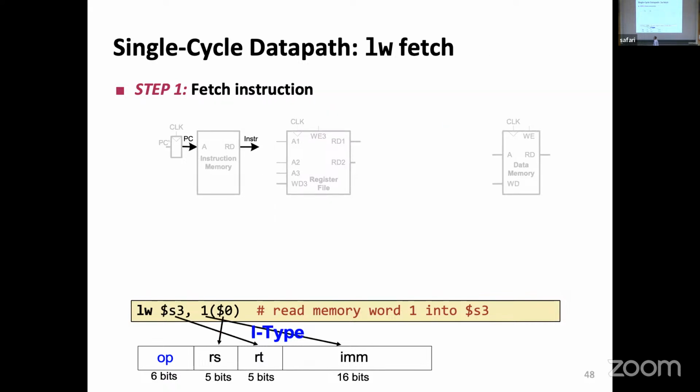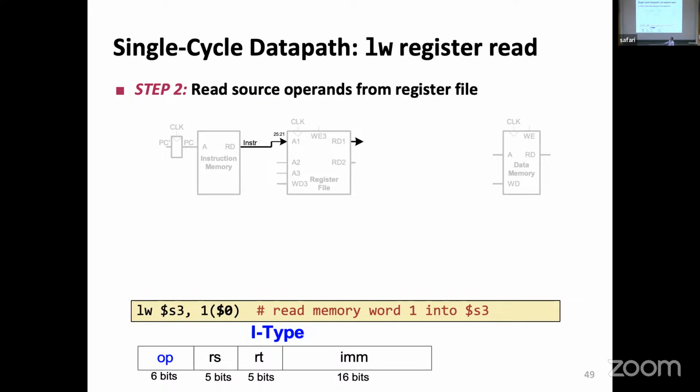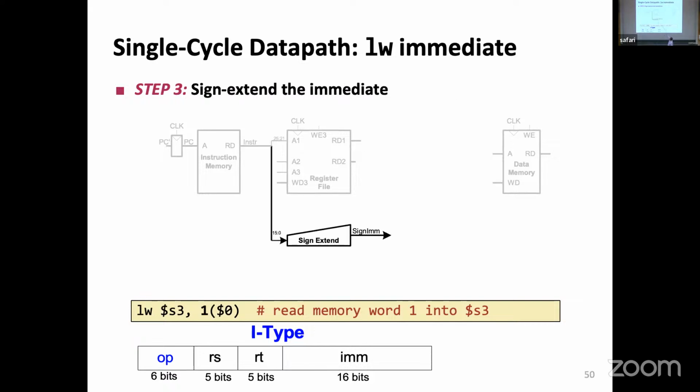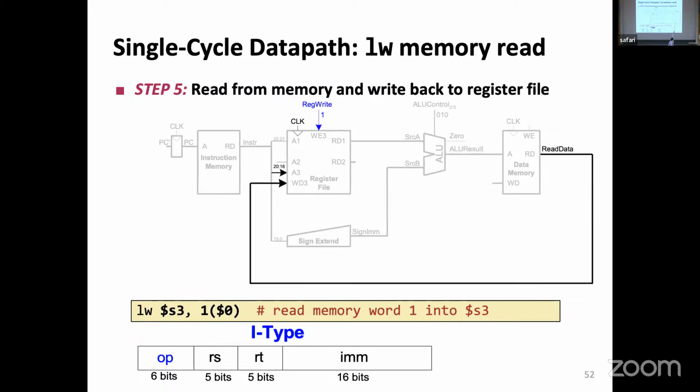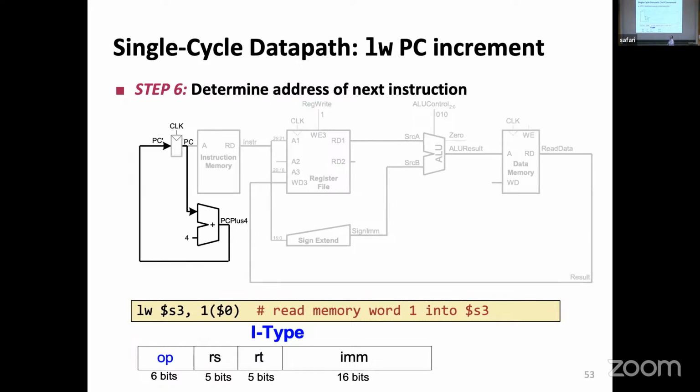And you see, these are the same steps that we are discussing here. We fetch an instruction. If you follow from the board there, we decode what it is, then we read the source operands, we combine them together, we perform the operation, we get the data, we write it to where it needs to go, and then we repeat this cycle. To repeat the cycle, we need to point to a new address, and at the end of the cycle, I have my new address. Questions so far?